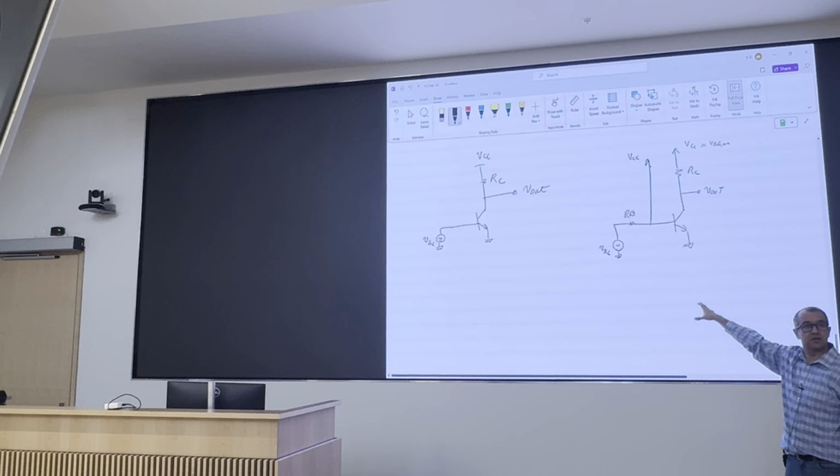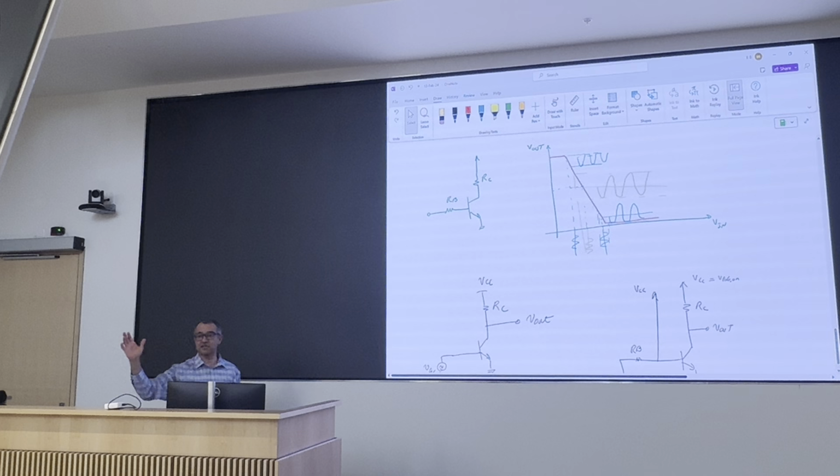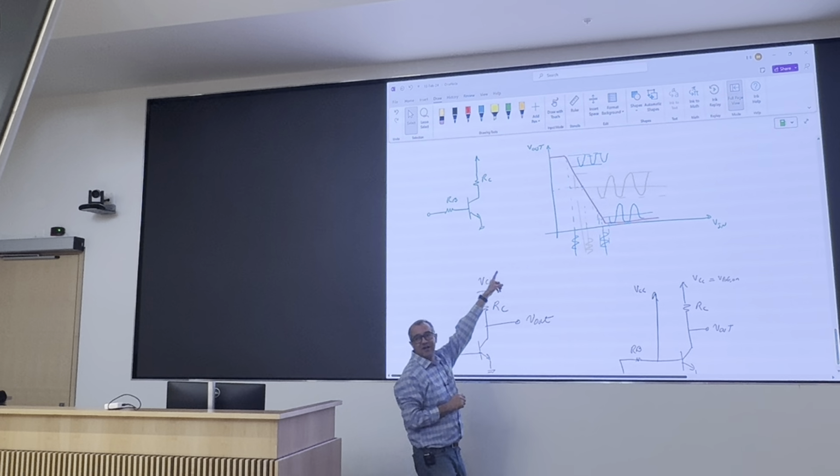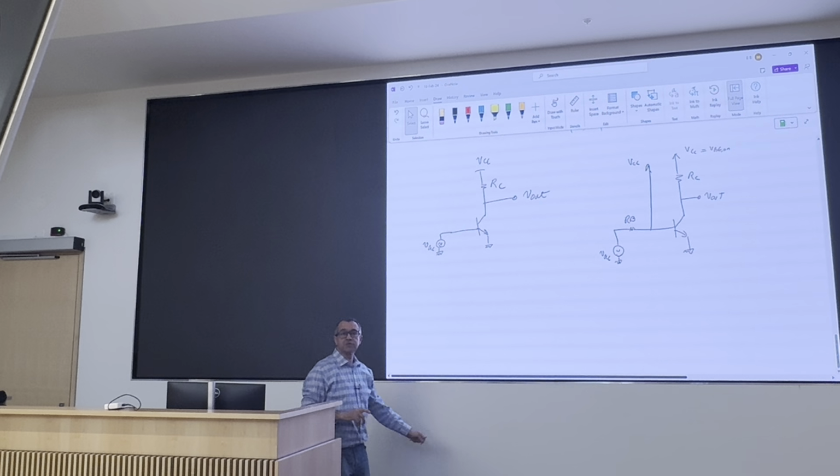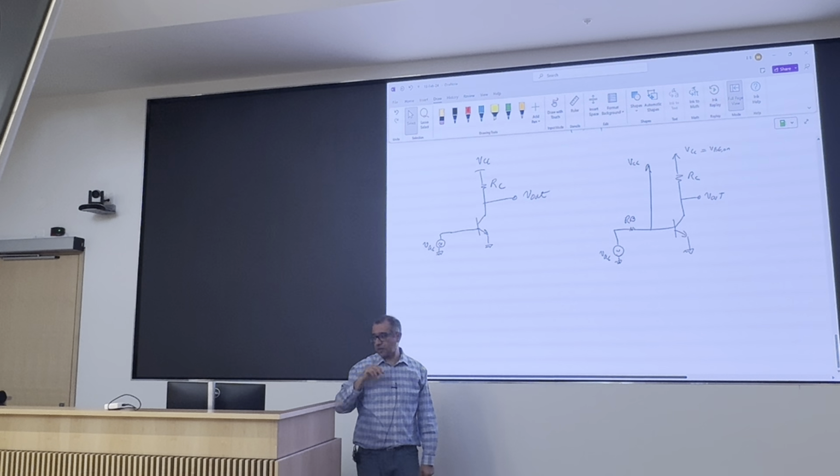No, I'm happily biased. Maybe unconsciously. But I'm biased, right? So I have some IC, some VCE that is, let's say, 0.3 volts, 0.4 volts, because the VCC is only 0.7. But you measure 0 at the output. Why?